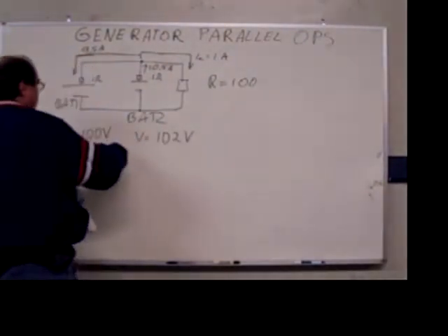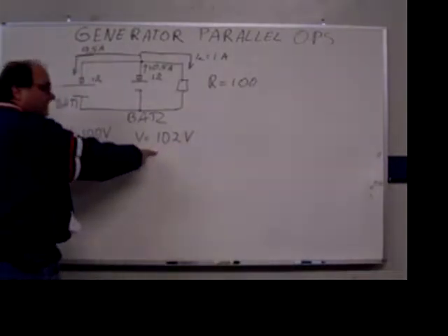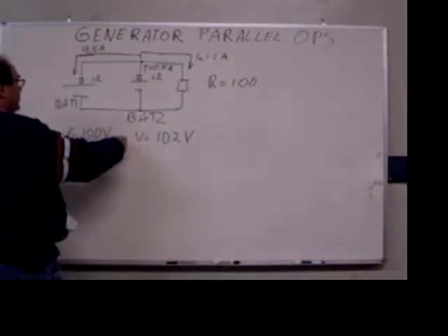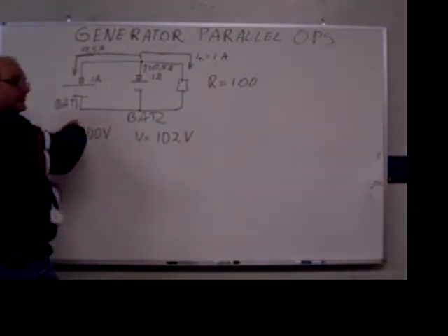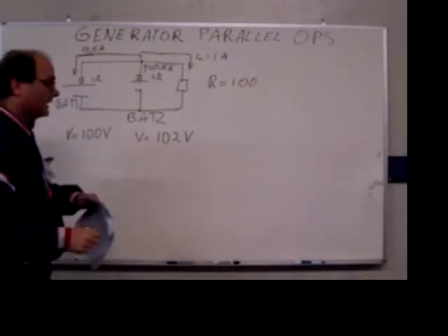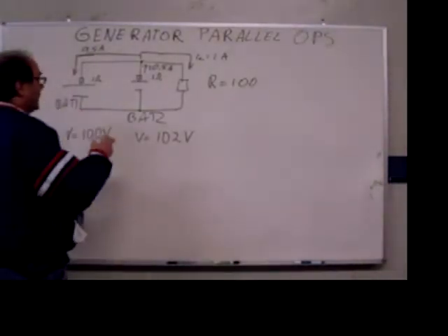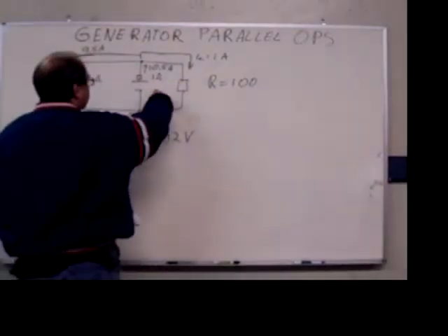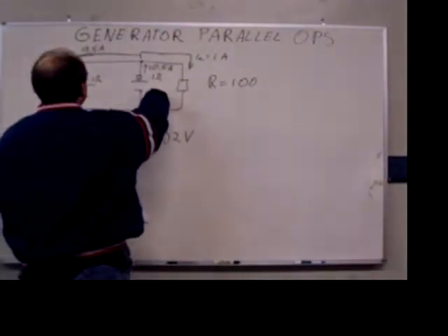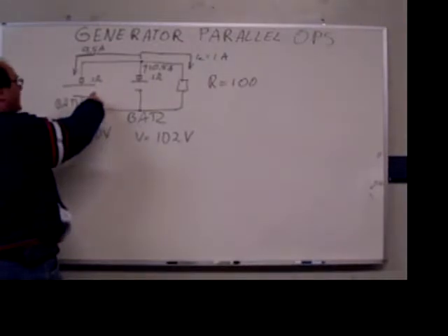Battery 2, since it has a higher charge and a higher voltage, is going to try to charge this other battery, bringing it up to the same level of voltage. They're going to seek an equilibrium. Besides the load current going through the battery, it also has to provide an additional 9.5 amps, which you can calculate from the internal resistance of the battery.